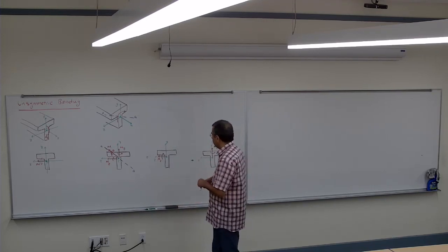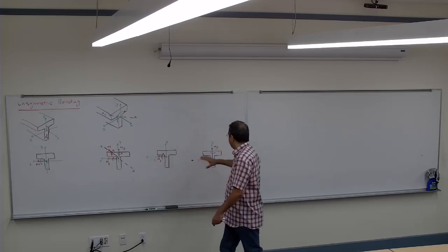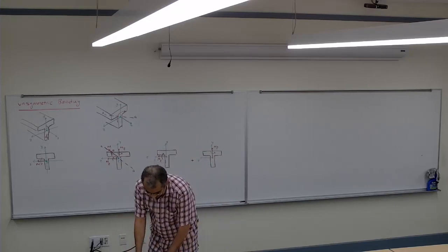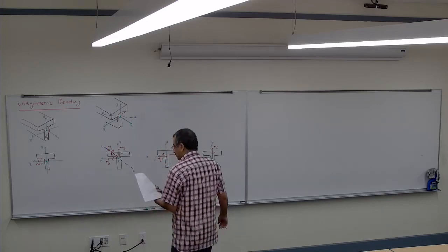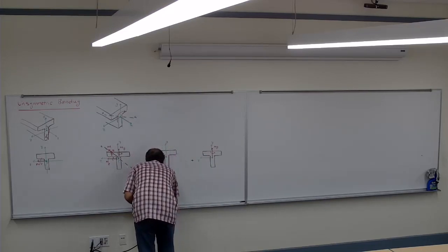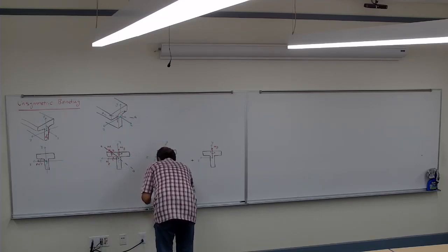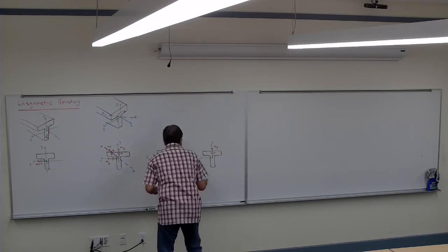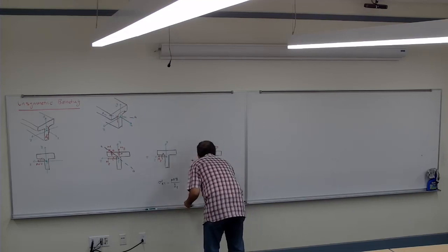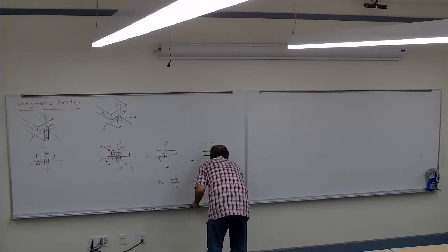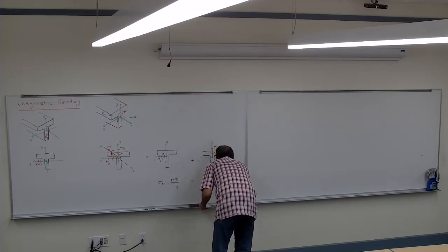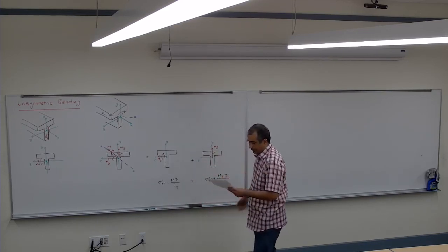Like that. So I have to calculate the stress once for M about the z, and once for M about the y, and then add them together. So in this case, if you look at what we have here about the z, I can go ahead and say, okay, the sigma x would be negative M_z y over I_z, plus the sigma x for the other one, plus M_y z over I_y. And then I add these together, and it gives me the total stress.